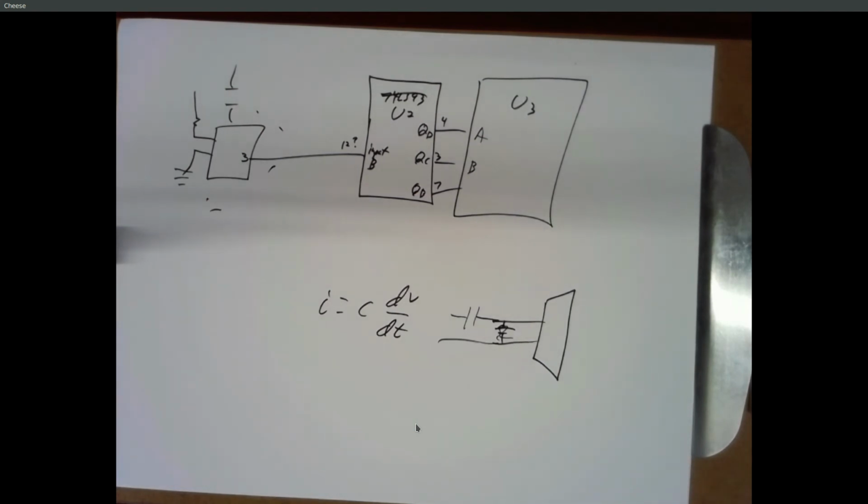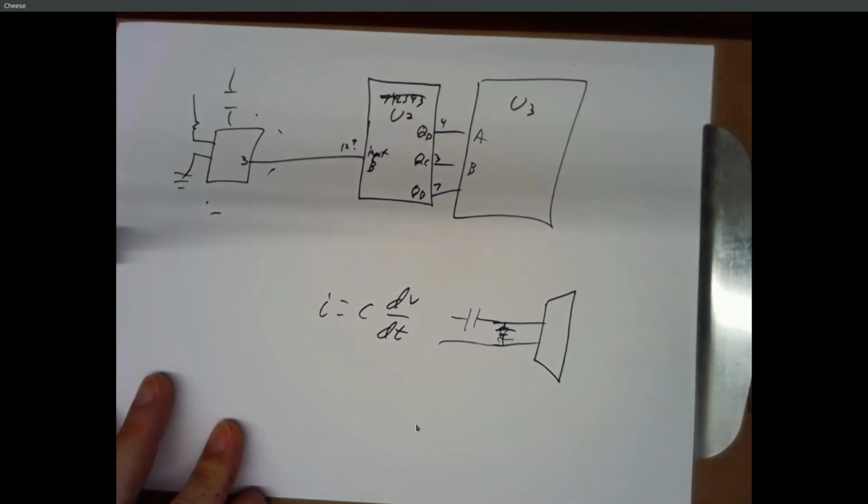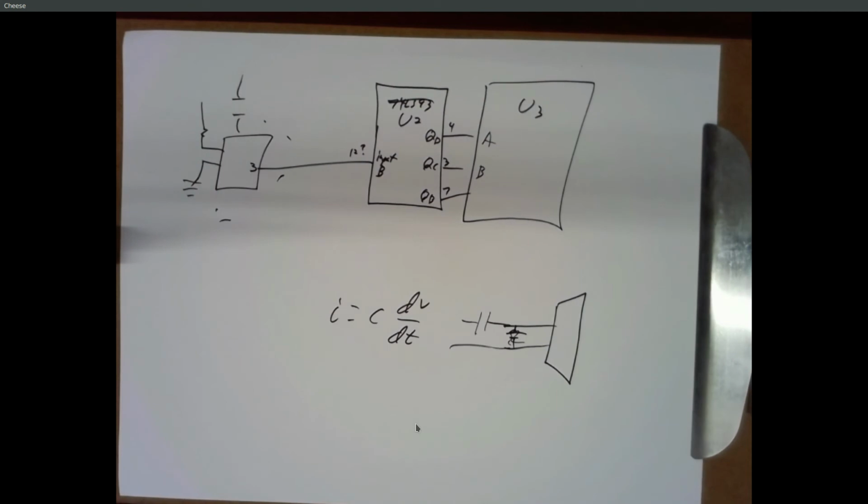And you use them in cars. Your headlights tend to blink out whenever the bass thumps, right? So you put a capacitor in the headlight system and it will store extra charge, and when your bass hits and your speakers pull a lot of current to move the woofer to push a lot of air, the extra current that your headlights need comes from this big capacitor, and your headlights stay lit. And so you can find giant Farad-sized capacitors. There's a cool one called the Raptor. It's got like a T-Rex on the front or something. You can find these things to put into your sound system in your car.